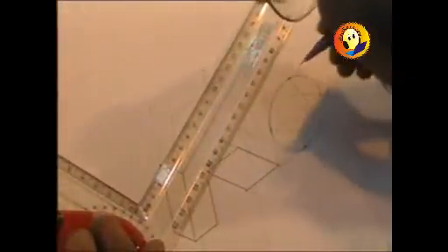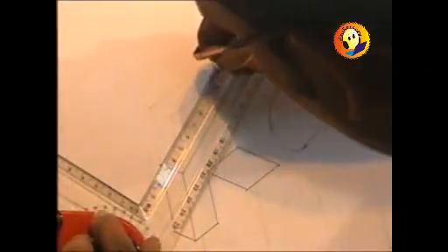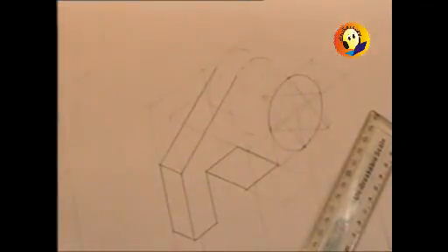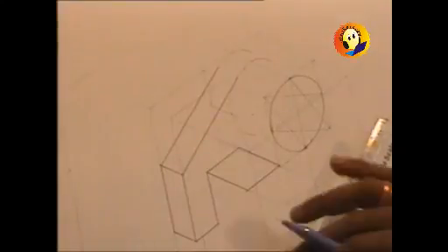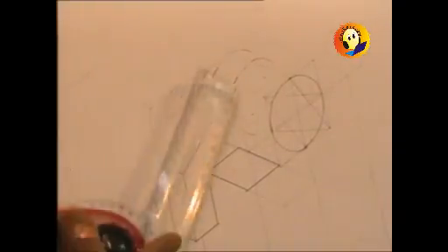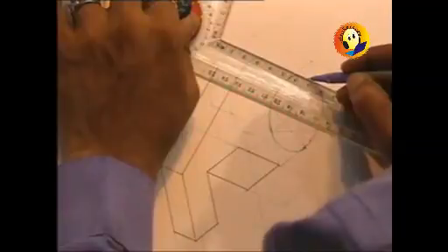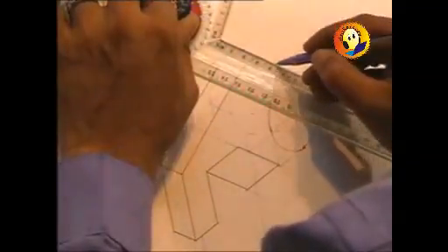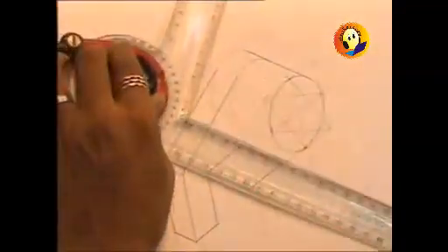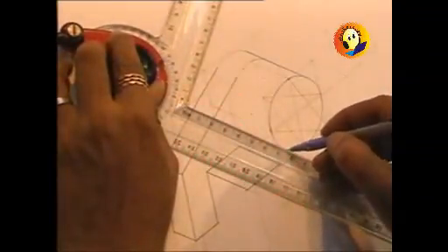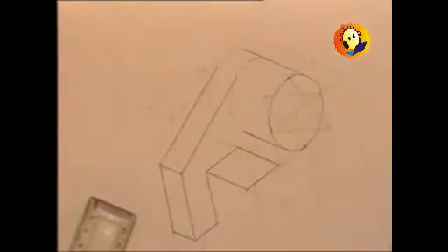And of course from the back also it will be the similar construction up to the tangent. So this portion can be drawn. And now to complete the cylinder, we are required to draw a common tangent which will be at 30 degrees angle only, and a common tangent over here, but it will be up to the plate only. This is how the construction is to be done.